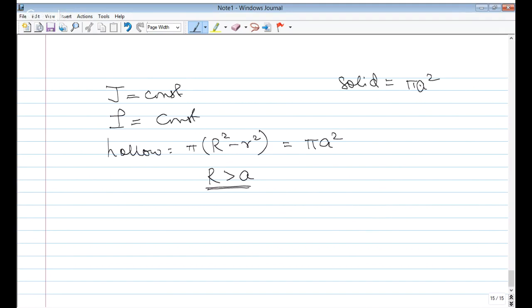So if radius is increased, the electric field, which is Q by 4 pi epsilon naught R, or in case of cylinder, it is rho by 2 pi epsilon naught R, will decrease. If electric field decreases, corona loss will reduce. So what we can say is current density will remain same, but electric field will reduce. In 260, the insulation of modern EHV lines is designed on the basis of switching over voltage, and for low voltage line, it is the lightning over voltage.